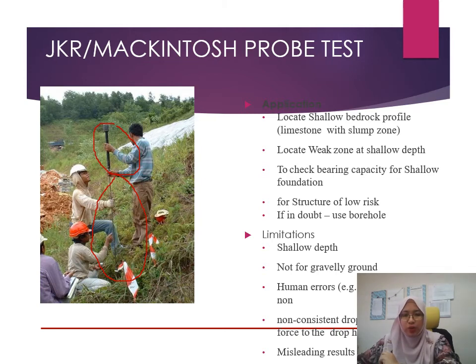We can locate weak zones at shallow depth. We can also check bearing capacity for shallow foundations and for structures of low risk. So it is only suitable for light structures. If in doubt, you can opt for a borehole, using drilling operation.